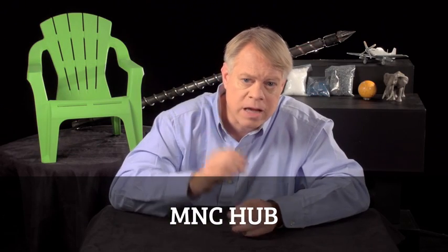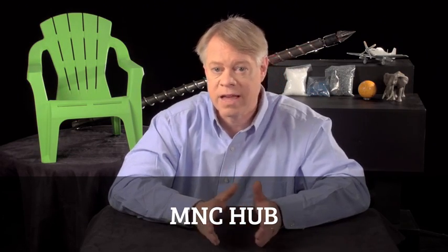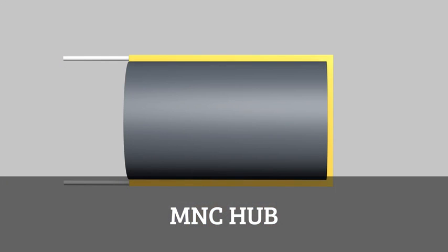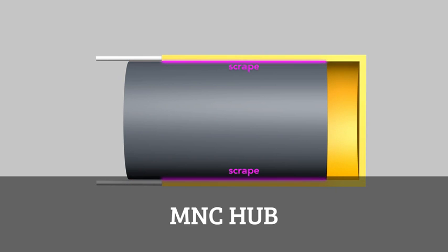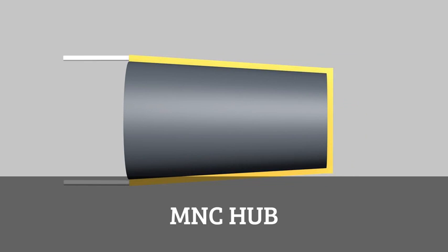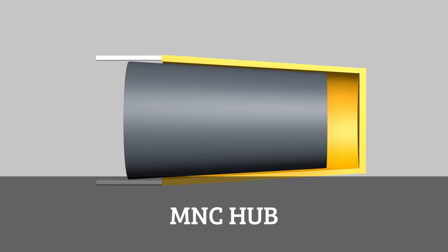Another very important aspect of mold design is the draft angle. If a part has walls that are exactly 90 degrees, it will be very difficult to eject because its inner walls will scrape the core half of the mold. Also, the vacuum will be difficult to break because air cannot readily enter. However, if the walls are slightly tapered, even just 1 or 2 degrees, it becomes much easier for the part to be removed because once the part moves slightly, the walls are no longer in contact with the core half and air can rush in.